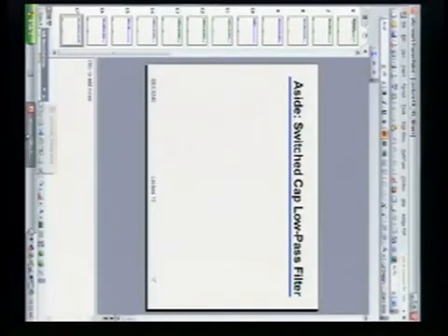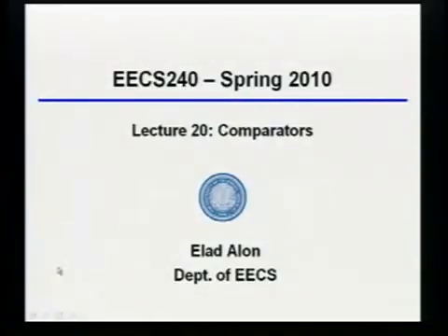So the next topic we're really going to talk about, as you might guess, is comparators. Okay, and so the reason I'm going to be talking about comparators is we've already talked about transmitters. We've talked about what the channel looks like. We've talked about how you might build the front-end amplifier and the equalizer. So really the last component we need to build a full link is the comparator that we're going to use as our receiver.